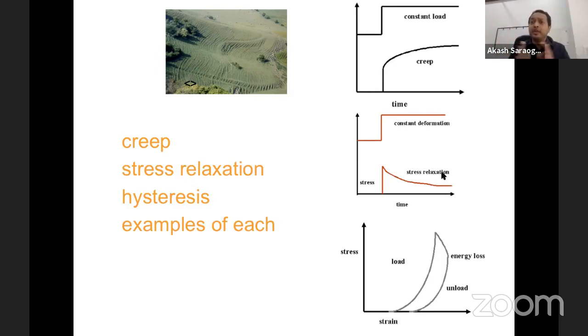The stress is very high because there is a hoop stress happening on the stem of the femur. Now, that stress level goes down after a few minutes, because if you hit the ultimate stress in the very beginning, the stem is going to fracture. That's why you want that stress to come down. You want a stress relaxation like this so that you can tap again and you can increase the stress again and get the stem down. So this is one example.